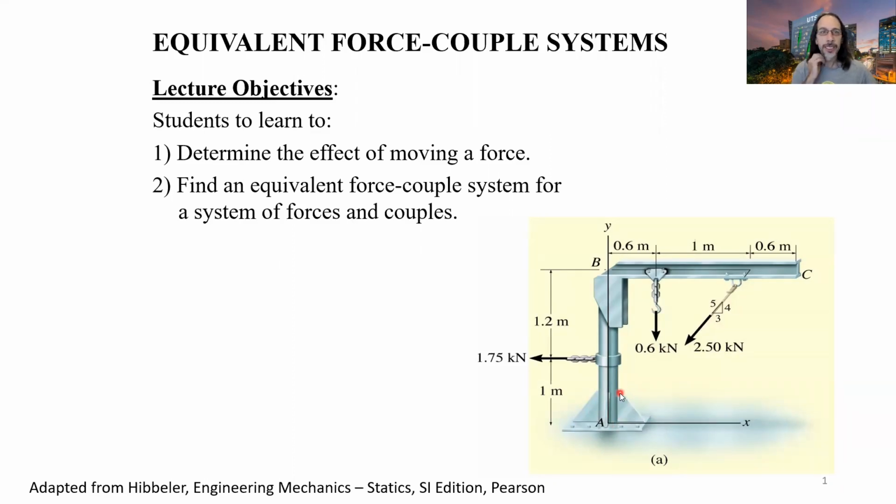And when you get to later subjects where you do those kinds of calculations and those kinds of detailed design problems, usually what you need to do is to find out the normal and tangential force or shear force and the moment that's applied at this location when you're calculating these bolt loads and the size of the bolts that you need.